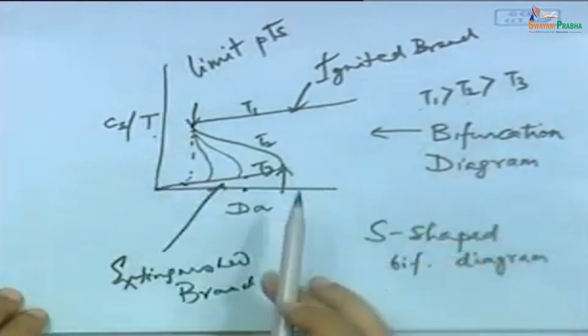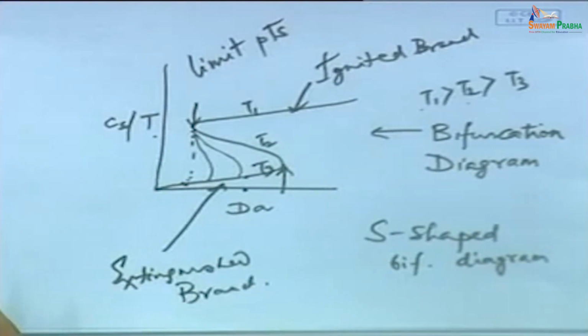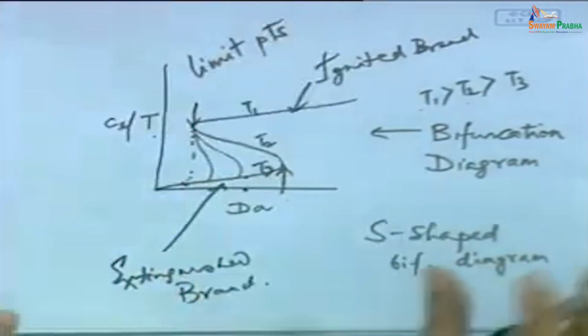The second possibility is that within the same CSTR, you can have regions with temperature T1, T2 and T3, and that is where the issues of instability, multiplicity and reactor runaway come in, as I explained in the other class. This was a prelude, and the reason we did that was because substrate inhibition is a sort of catalysis. It is an inhibition, but you can have a catalyzer also. So it is an auto inhibition or autocatalytic effect.